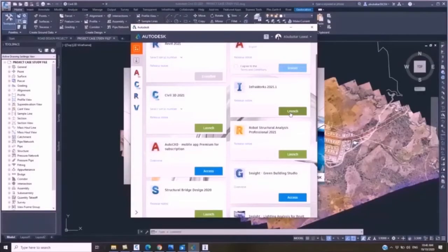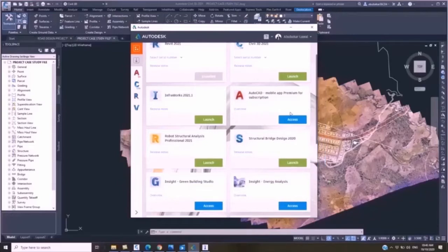Before we could start, based on the work that the town planner had carried out, and because the surveyor had not done the detailed survey of that area, we had to use a faster means of getting our survey data by flying a drone on the site, with control points to get the ground control details and exact survey data, which gives us an accuracy of 0.1 plus or minus.